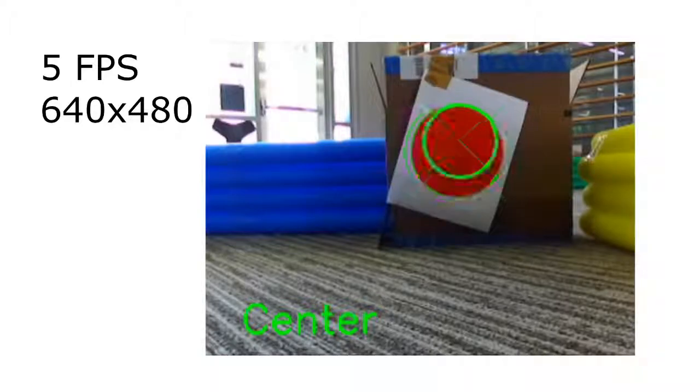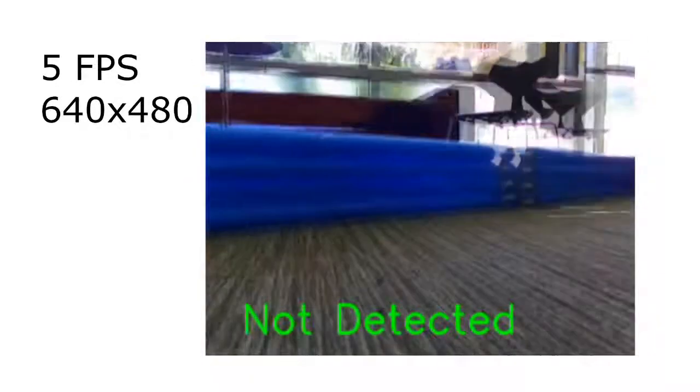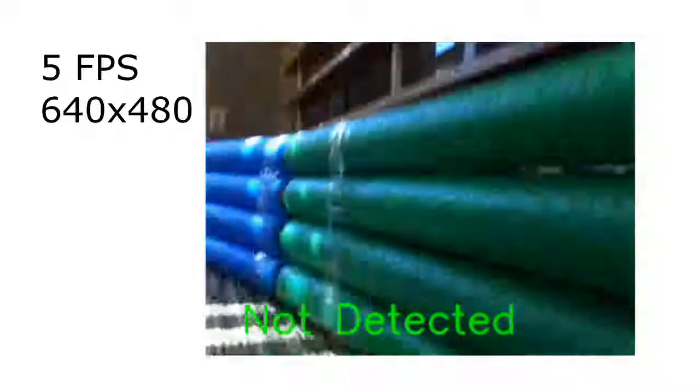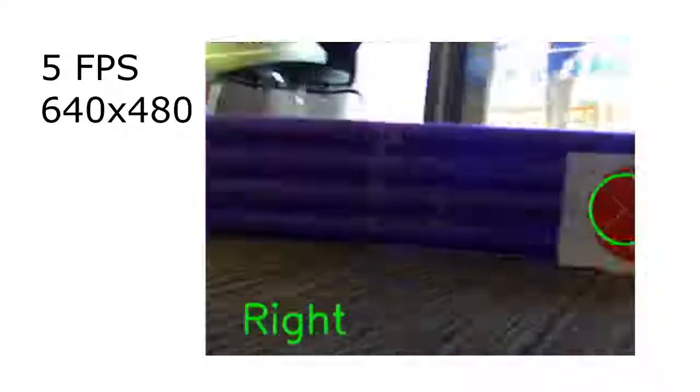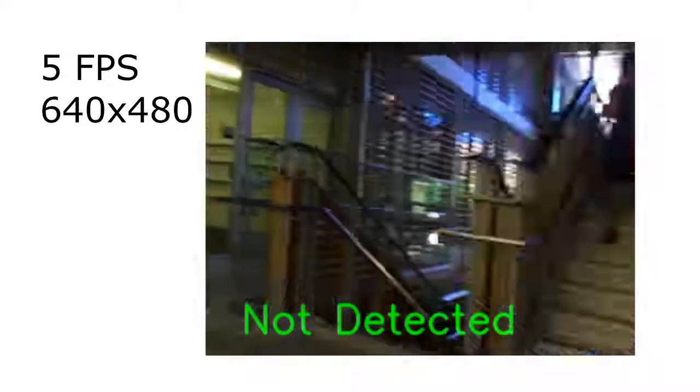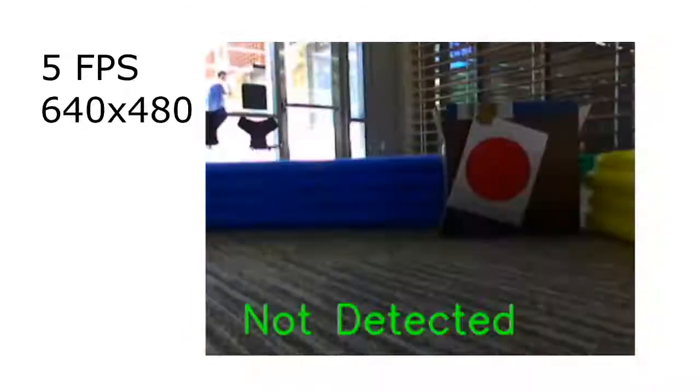What you can see here is the footage of the ZED camera with information gathered with OpenCV overlaid on top of it. We can gather information about elements on each frame, such as the position and radius of the red circle. While detecting red circles, it is very easy to get false positives, so the controller filters them out by only considering circles of a certain radius.